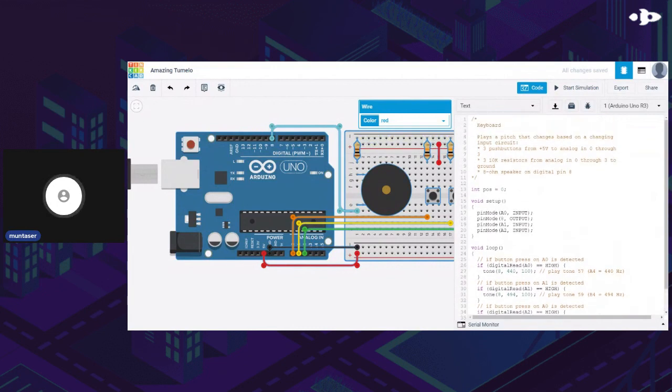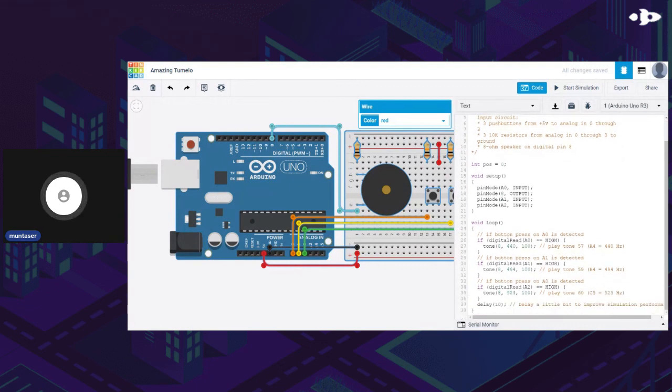As you can imagine, this requires a little bit of setup, so let's set up all the pins. We have the A0 input. Nomenclature wise, if you want the analog pins, you need to put an A in front of the pin number. So that's 0, 1, 2, 3, 4, 5, and this is A0. For the digital pins, you don't write D, they're just normal numbers. So A0, A1, and A2 are input pins. Digital 8 is an output pin.